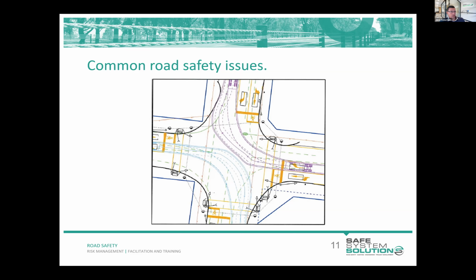So this really looks to be a situation where an intersection has been designed within a confined space. Some swept paths have been plonked on top, and an attempt has been made to show that these vehicles can get past each other. The desirable thing to do would be to construct these swept paths on a single radius in accordance with guidelines. And if that was the case, I think you'd see quite an overlap within the middle of the intersection of these swept paths.